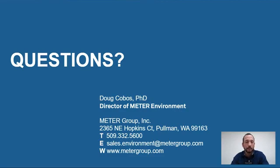But then to get a broad range of water potential measurements all the way from close to saturation down to maybe permanent wilting point, you probably are going to need to use one of the granular matrix sensors like our Teros 21 that actually measures the water content of the ceramic disc that's in equilibrium with the soil, or something like the gypsum block sensors, or a variety of other sensors that either use thermal or capacitance or resistive techniques to measure the water content of a material that's in equilibrium with the water potential of the soil. And so those measurements are advancing pretty rapidly and getting more accurate with time.